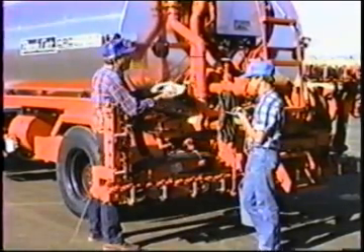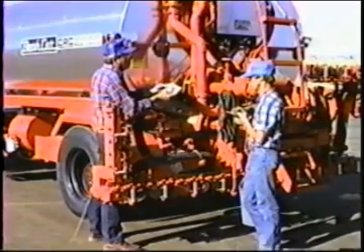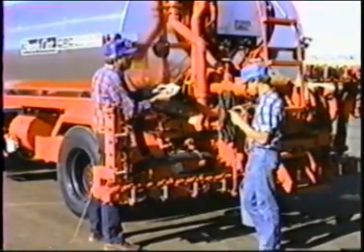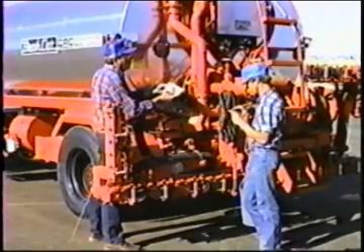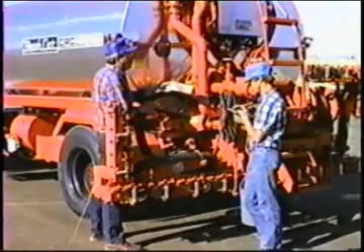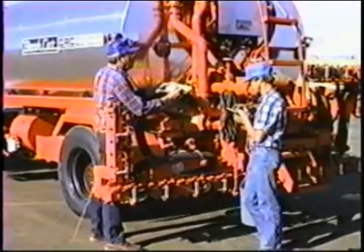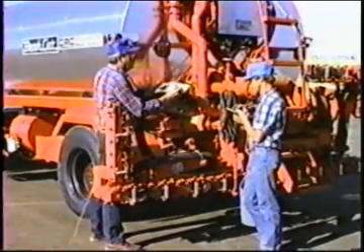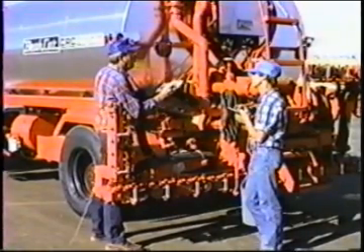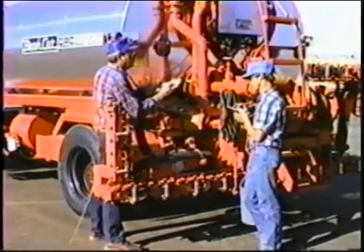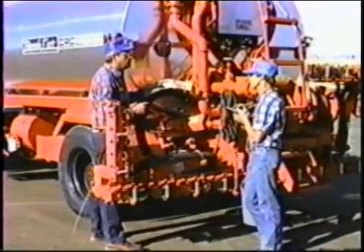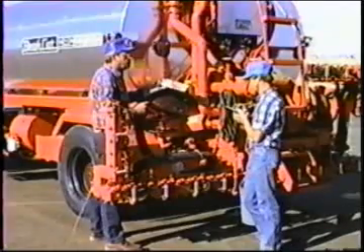Now if we make a change, if we were to speed the truck up and move from 400 up to 500, align 0.25 at 500, you'll see that our pump speed has gone up to, still looking over the 12 feet, 170. 0.25, 500 feet per minute, 12 feet wide. That's exactly right, 170 gallons per minute.